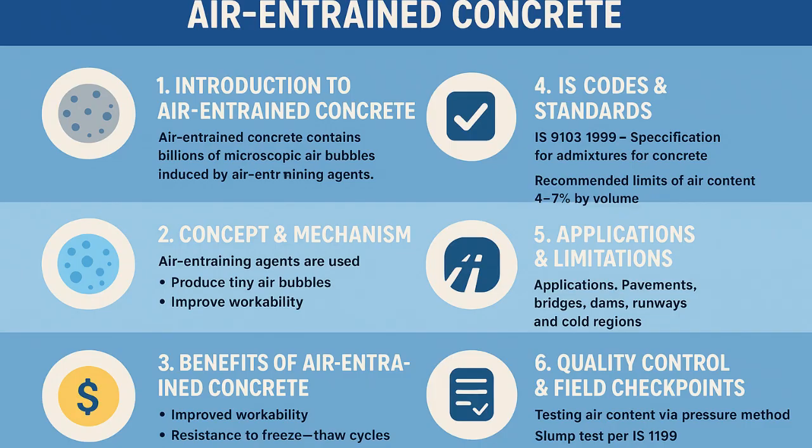These bubbles act as tiny shock absorbers, giving concrete the flexibility to withstand freezing, thawing, and other stresses. Unlike normal concrete, which is dense and rigid, air entrained concrete maintains durability even in extreme environments, making it highly reliable for pavements, bridges, and runways. So, this is air entrained concrete.